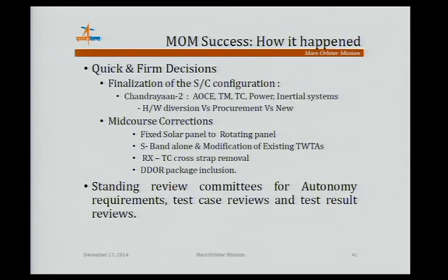Then for the S-band system, there were two options, S-band or X-band system development, and X-band was dropped and only S-band was used here so that it minimizes the time for realization. Similarly, the cross coupling of receiver to telecommand system was simplified, and a delta device package was included. This was required for accurate measurement of the range and range data, and the trajectory plane also was determined using this. This was introduced, and reviews.